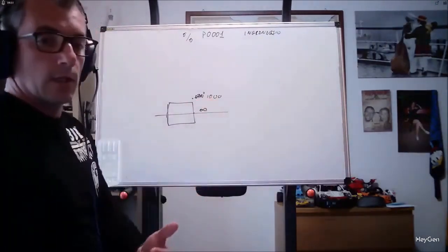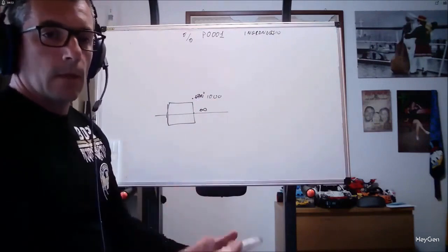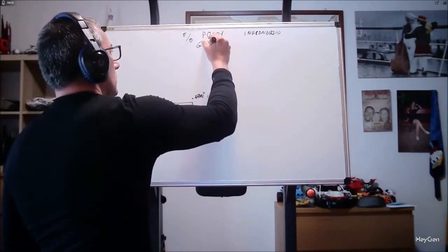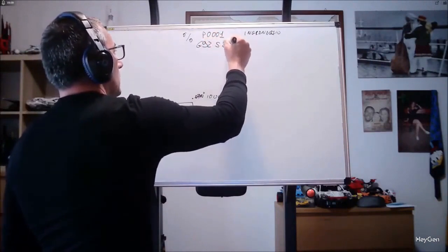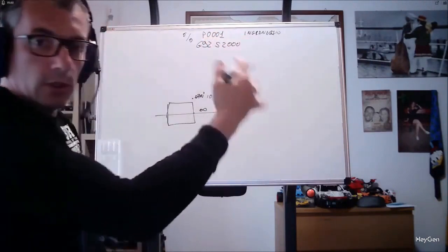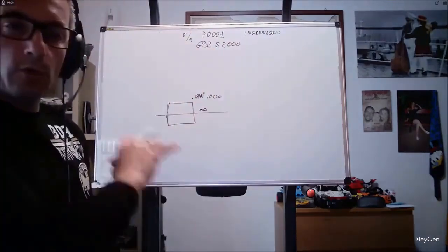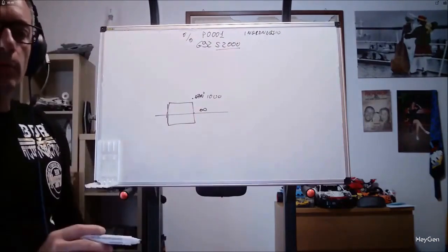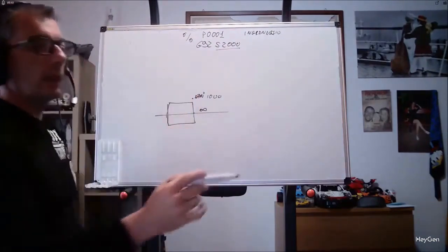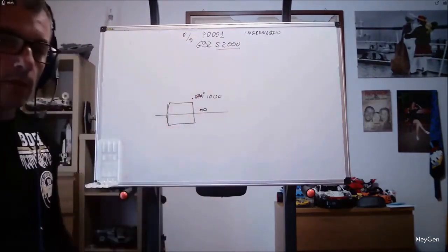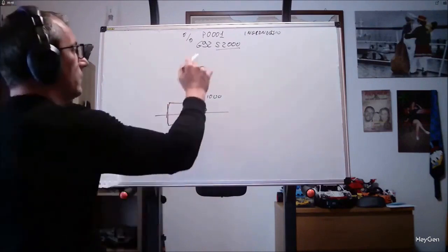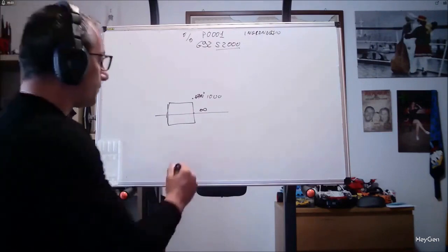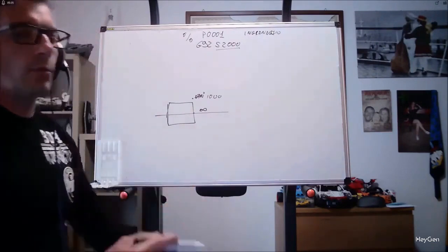So normally, depending on the type of machine and the weight of the piece, and some variables related to the grip, we write G92 S2000, 3000, 4000, 5000. That is, we tell the machine that at any moment during processing, you can never exceed these RPM numbers. G92 is repeatable within the program, meaning if we perform multiple operations and want to change the maximum RPM for safety reasons, we can do so. So if we have a piece weighing 80 kilos, we can do it.